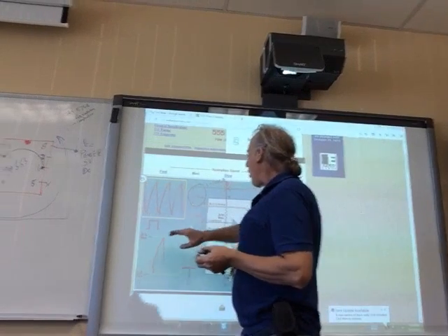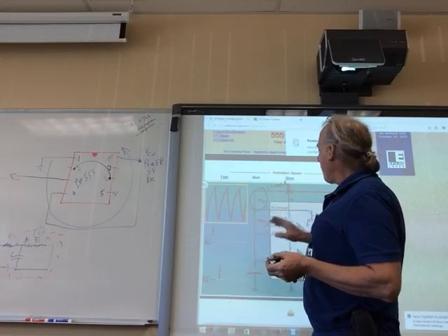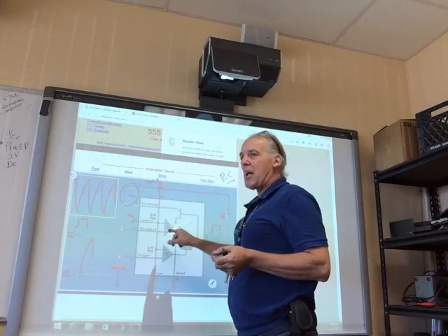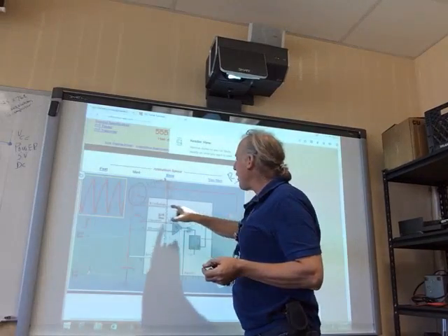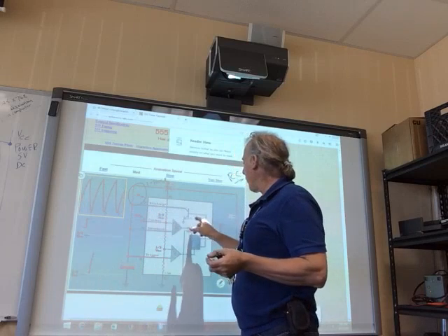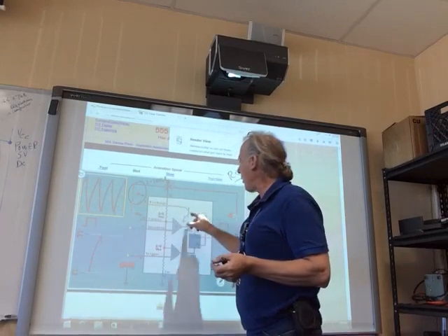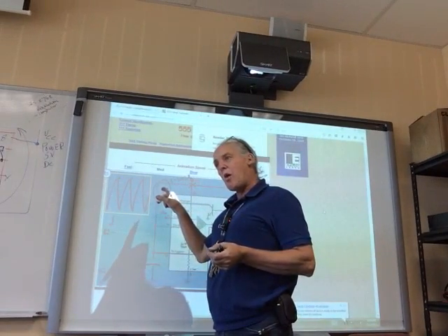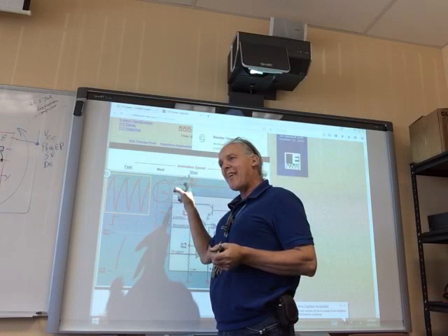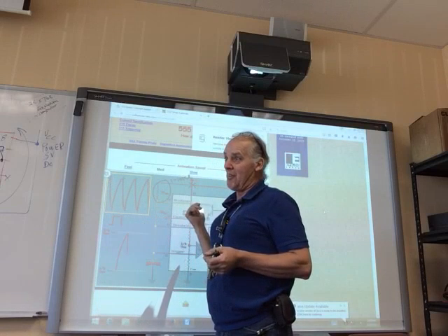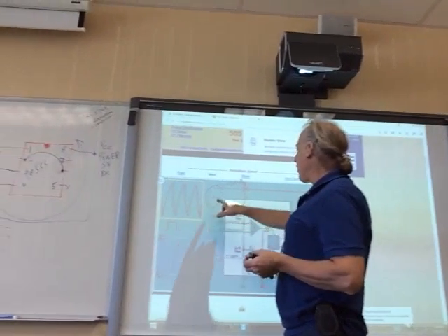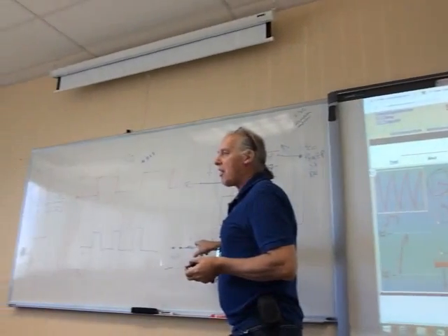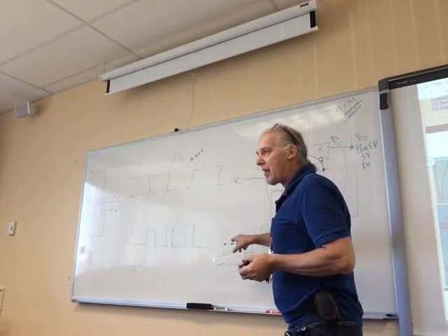But it never gets all the way up where it gets flat, because what happens? The circuitry in here says, okay, I'm done. And it shorts it out right here with this transistor to ground, shorts that out. Now, if we didn't have that resistor in there, what would it do to the supply? It shorts the supply out. So the reason that resistor's in there for here, because it doesn't really matter here, does it? I mean, we could use it just right from the supply, couldn't we?